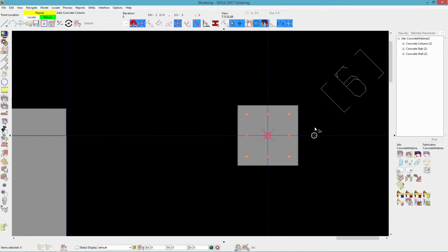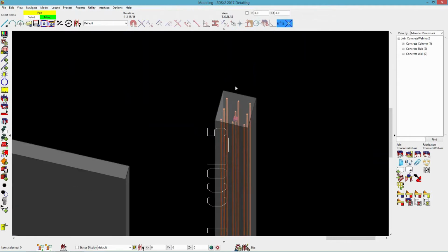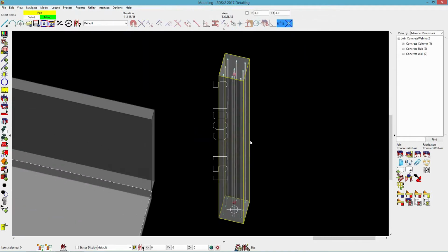And now when I zoom in here, you notice that I have my 1'6" by 1'6" concrete column there, and I have my vertical rebar. So the main question when you're looking at it is, I've got my vertical rebars, but I do not have any of the ties that I put in. The 1 T2 tie and then the 2 T9 ties are not showing up here.